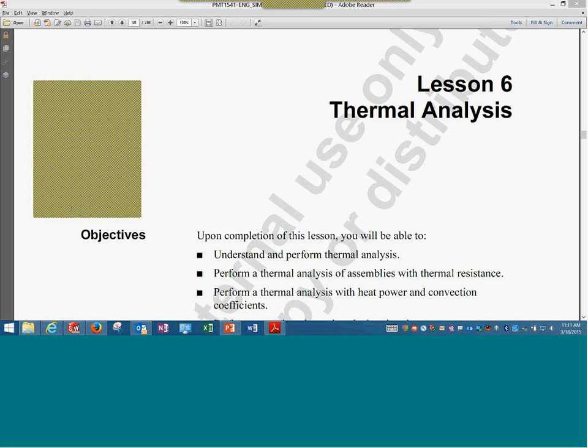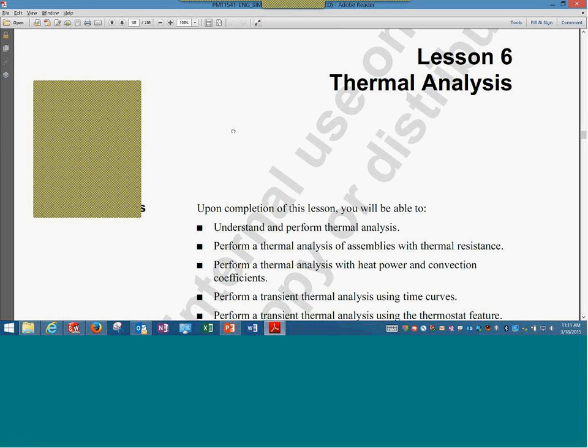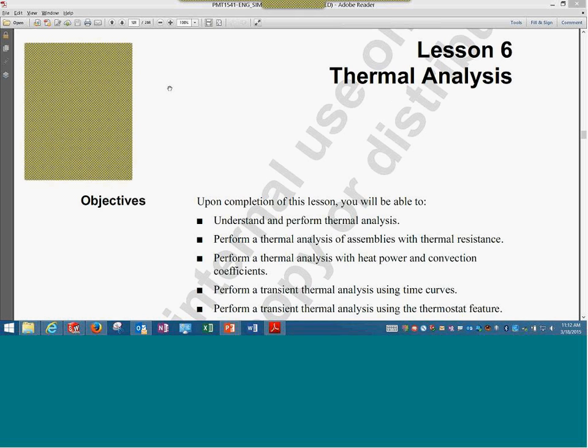Otherwise, there could be cases wherein there is a localized specific component where you see the stresses, but the stiffness of the entire geometry is equally important. Do not neglect the entire assembly. In such cases, you can do a coarse analysis of the entire assembly to set the stiffness of the assembly. Thereon, on the local component, you can do more detailed analysis. That's the process. I'll give a few more seconds before I jump into the thermal analysis.